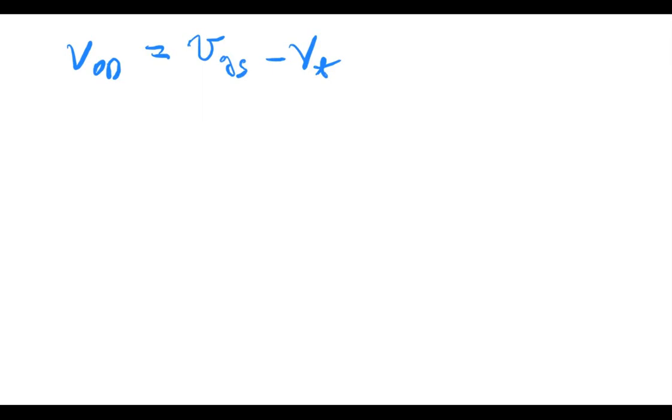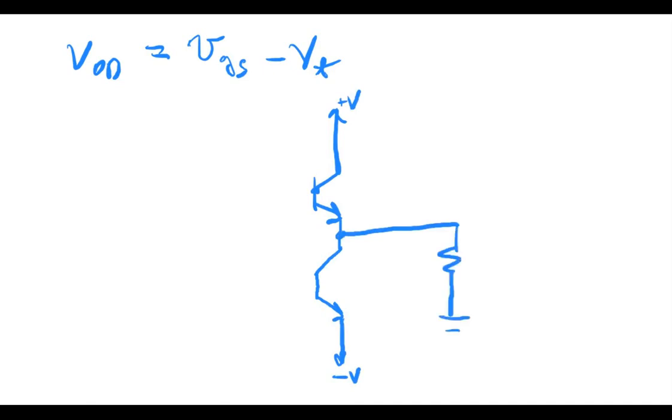That figure 12.3 is an emitter follower based amplifier, which has a positive supply here, and you have an NPN there. Here you have an active load. So this is minus V, this is plus V here, and here's the output, with the load resistor.